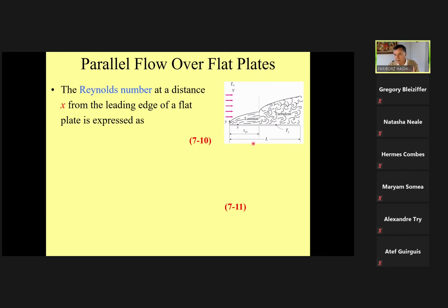When I calculate my Reynolds number, it becomes like this: rho times the free stream undisturbed velocity, because the velocity here is different from here, but when we calculate the Reynolds number, we use the free stream right here. I can change this, or I can use this equation. It is the same as this one, except this is the kinematic viscosity, which means viscosity divided by density.